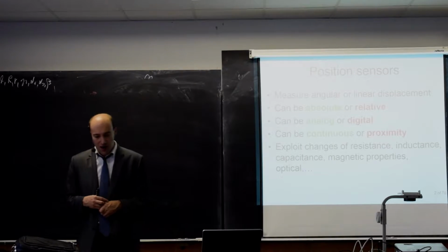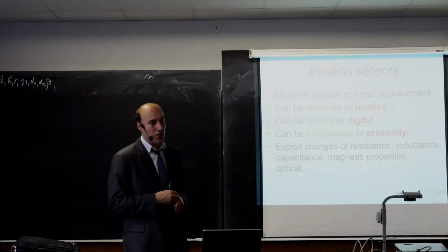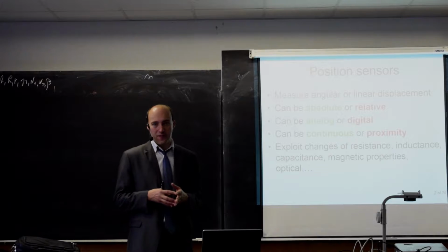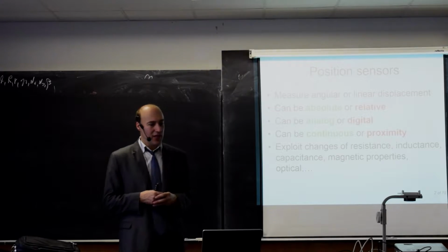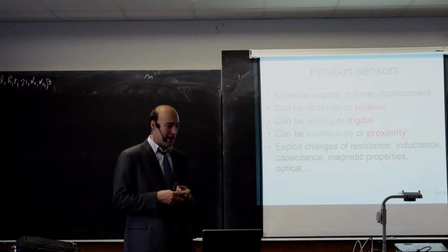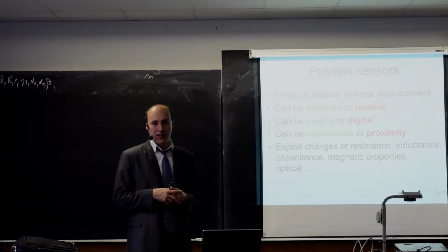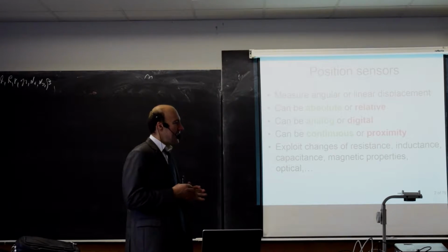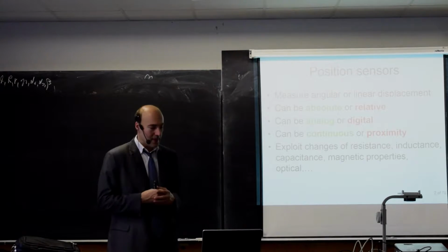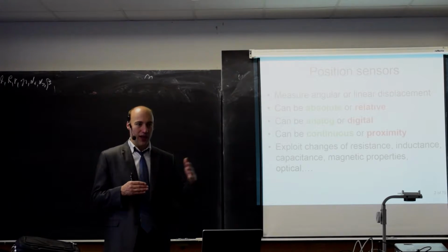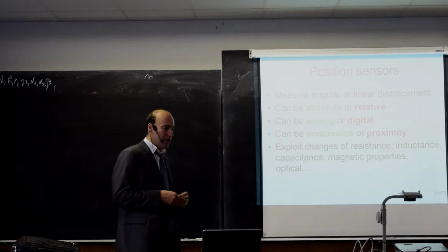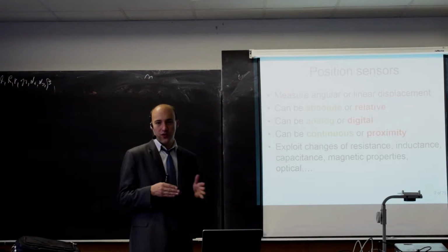On the other hand, there are applications like CNC machines, for example, where you require a high accuracy. It means you need a really high resolution for the sensor. And this is the task typically done by relative sensors. With relative sensors, when you start the application, you don't know exactly at what position you are. You make a reference movement to some end switch until it hits the end switch, then you know this is my 0 position. And then relative sensors count pulses from this position.